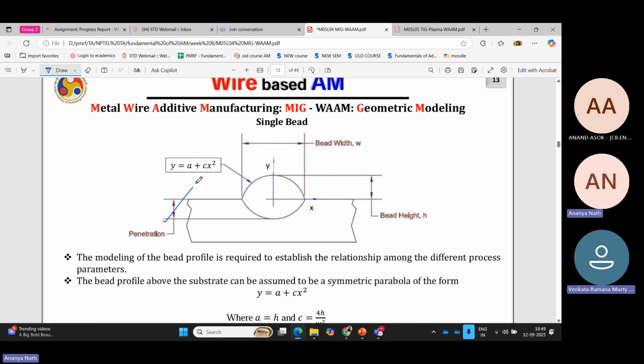And if it is remelting a lot of the melted portion, then it's going to be a problem. But whether the material is really penetrating into that earlier layer or it is just melted? A little top portion of the bead is going to be remelted.